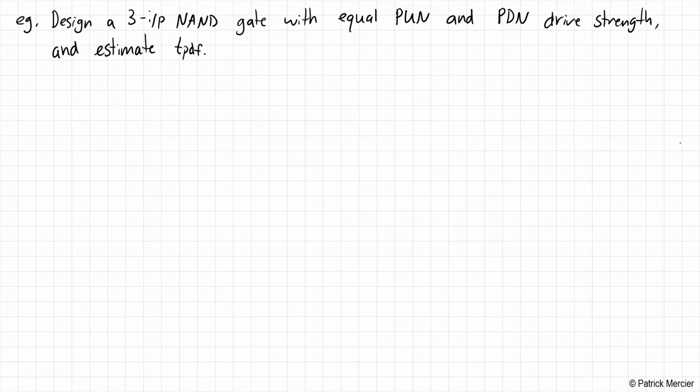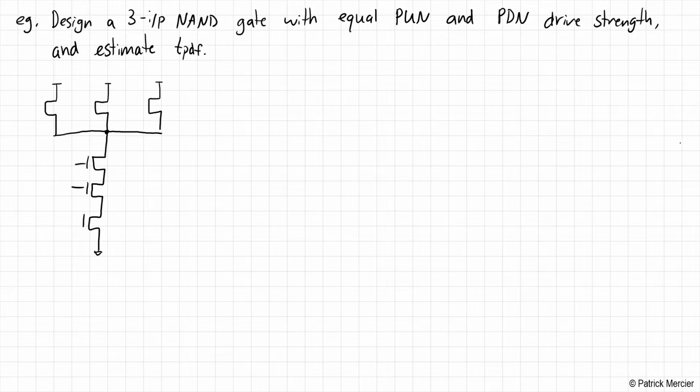First of all, let's go ahead and build our 3-input NAND gate. Now you could do the technique that we learned in one of the earlier lectures where we build up our device through Boolean algebra and useful constructs. In this case, a 3-input NAND gate is fairly straightforward. Essentially what we have are 3 PMOS devices that are going to operate in parallel and 3 NMOS devices that are going to operate in series. These are PMOS devices up here and our NMOS devices on the bottom.